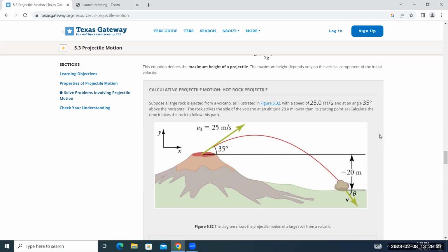The reason is because volcanic ash is mostly made up of molten rock. It's not just dust. So if we were to fly through that, that molten rock would encounter the blades on our jet turbine and immediately cool. And so now you have a jet turbine that's coated with rock unevenly. And if you've ever had an uneven load in a washing machine, you know what that sounds like. Imagine what that does to a jet engine spinning at 36,000 RPM, revolutions per minute. That can be extraordinarily bad and cause you to die. So we generally try to avoid volcanic ash clouds.